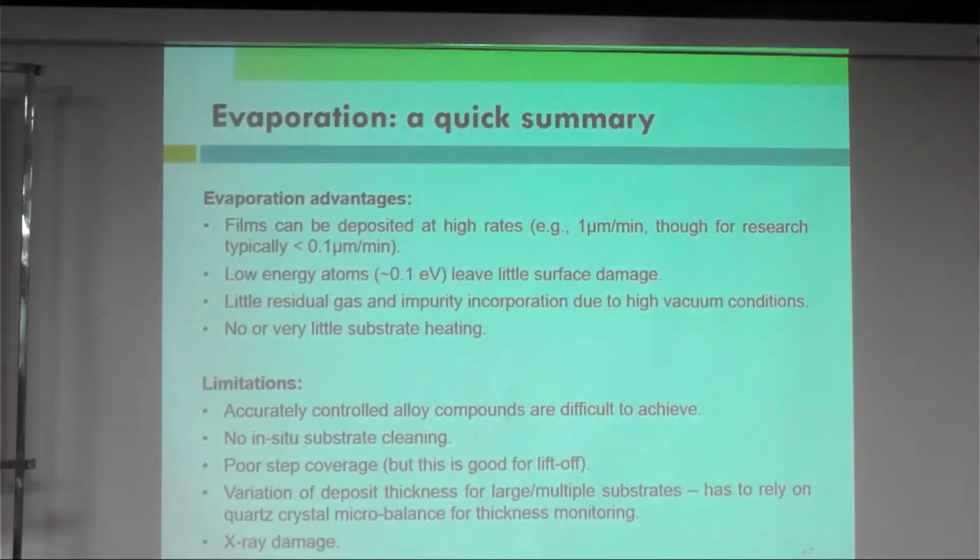So in summary, for evaporation, film can be deposited at high rates, for example, 1 micrometer per minute, though for research typically 0.1 micron per minute. It's low energy atoms, which leave little surface damage. There's no bombardment of atoms, little residual gas and impurity incorporation due to high vacuum conditions, and no or very little substrate heating.